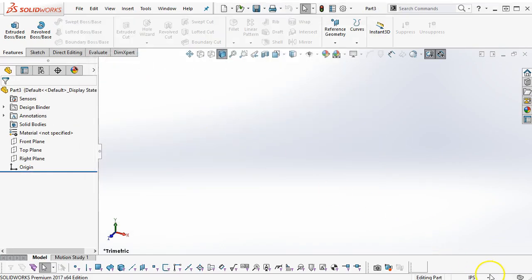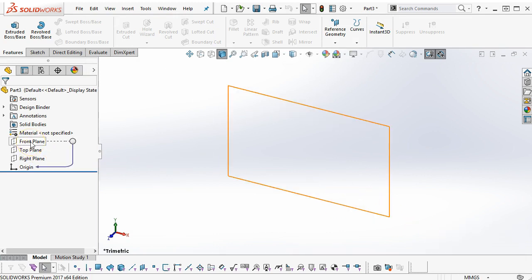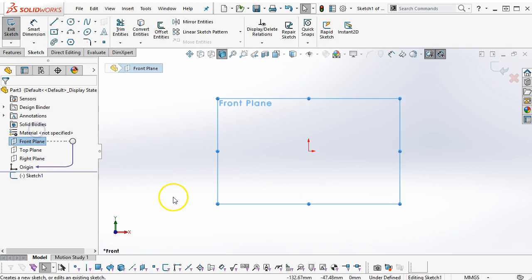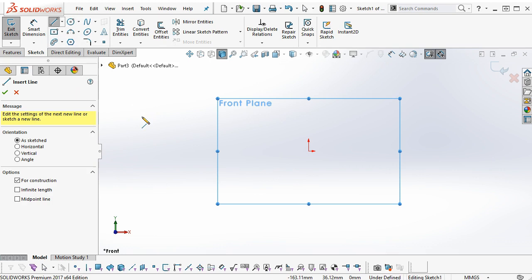New part, millimeters, grams, and seconds. And the peg would be easy enough to draw as a circle and extrude it out 20 millimeters. We don't have a lot of revolves, so if you want to create the peg as a standard, draw the circle and extrude it out, that's fine. I'm going to illustrate this as a revolve.